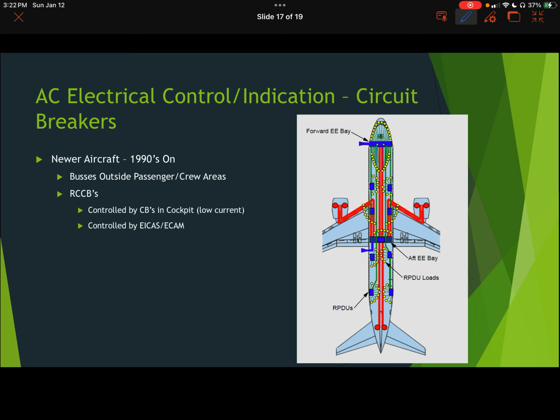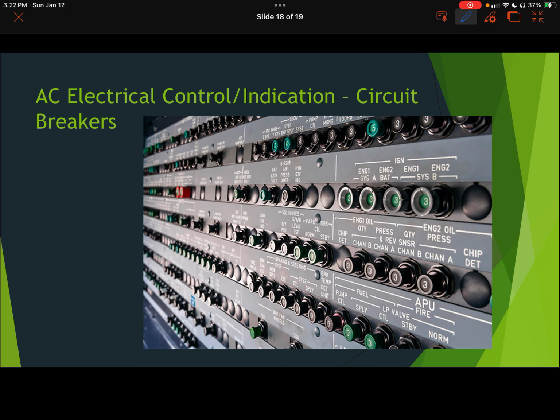Things like some avionics or smaller, some light bulbs and stuff like that. The distributed loads that are throughout the rest of the aircraft, those are your high current loads. Those are the things like the hydraulic pumps. Those are the fuel pumps. In the 787 case, it actually has electric motor-driven superchargers for pressurization and environmental control. Those are your heated leading edges in the 787. But again, high current loads in order to do that. So that's why.